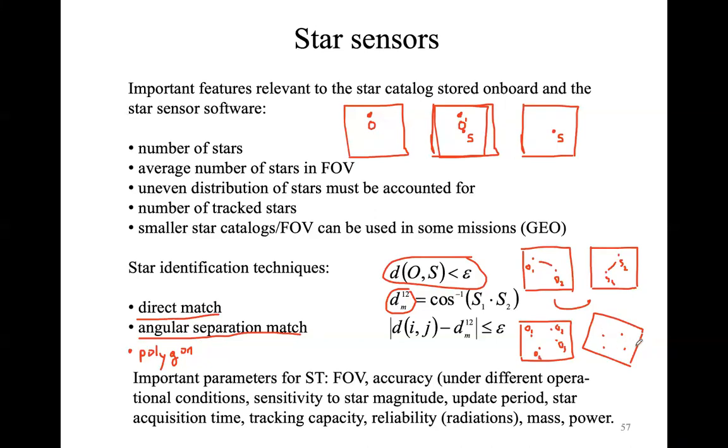Here you have something different because here will be S1, S2, and S4. So if you use multiple stars, so this polygon approach, by computing multiple relative distances from the stars, you are not going to have ambiguity because you are sure that this particular polygon configuration that you have is unique, and you are able indeed to provide the best knowledge of the attitude.